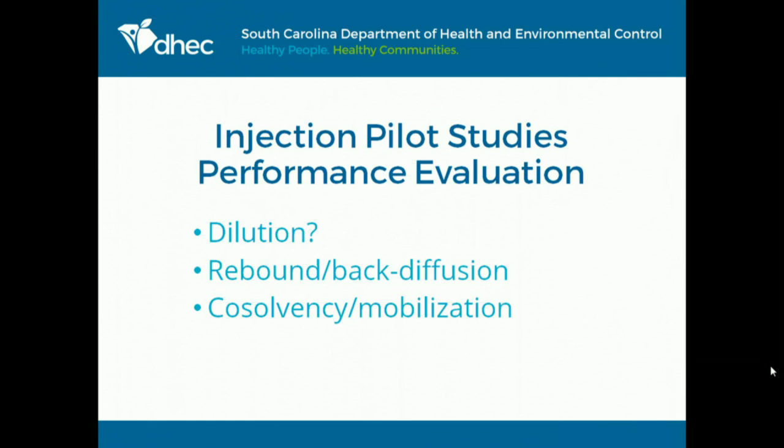Co-solvency. We were just talking during the break about emulsified vegetable oil, and there's actually a site, not in South Carolina, where they injected vegetable oil, and all of a sudden their groundwater concentrations went up into the tens of parts per million range when they were less than a part per million to begin with. And it turns out the vegetable oil actually extracted the solvent from the subsurface. And then they were smart enough to recover the vegetable oil, and they did a great job cleaning up that site. But that's something that's helpful to know during a pilot study.